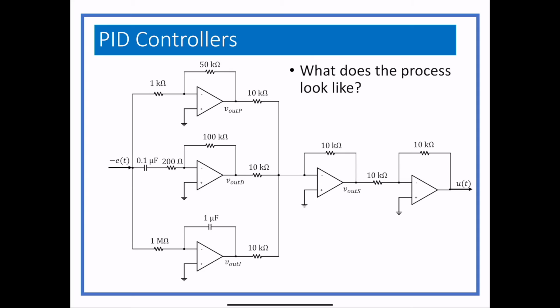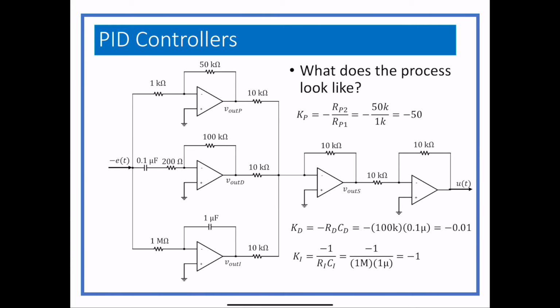But first of all, we've got a KP value for each one, which I can give you. Notice that the integrator basically has a K value of 1, the differentiator minus 0.01, so that's really small, and then the proportional one has a large gain. So those three working together are going to be used to figure out what the error is.